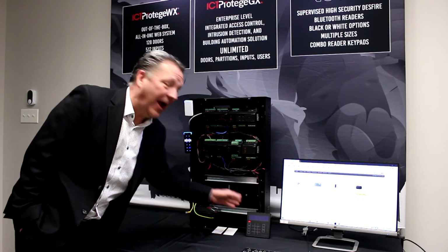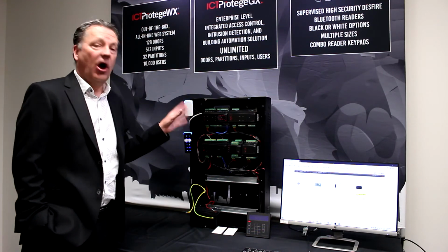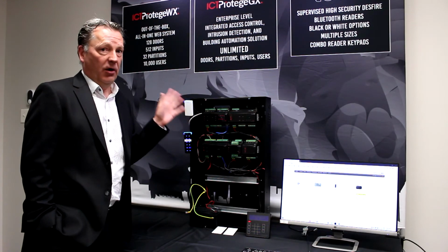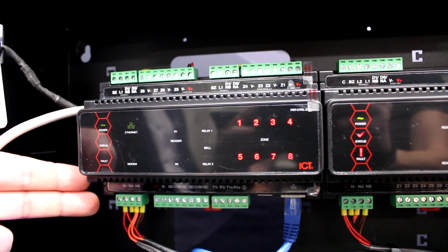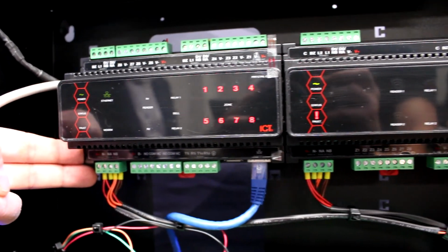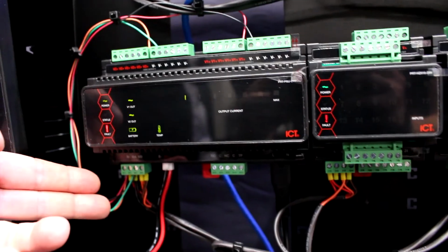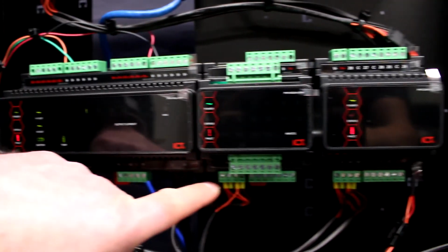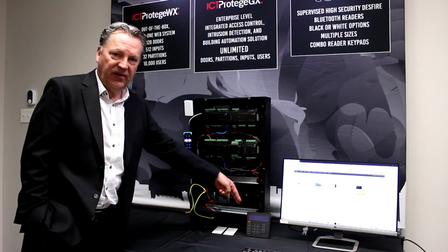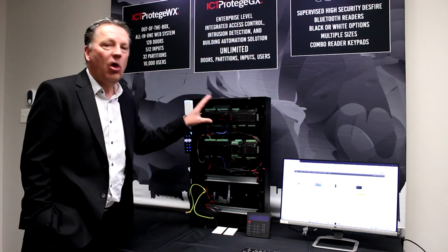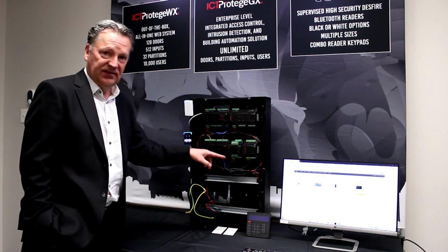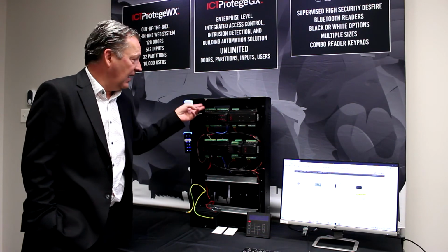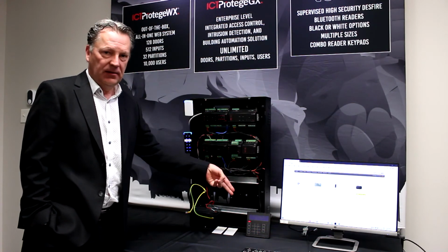Now, the wiring of the entire system is RS-485 wiring. The RS-485 wiring, in our case here, is starting from the controller. You can see it here. It goes from the controller to the door expander, to the power supply, to the 16 zone, to the 8 zone, and finally to the keypad. So it is all one complete RS-485 bus in a series after each other, terminated at the controller and at the keypad.